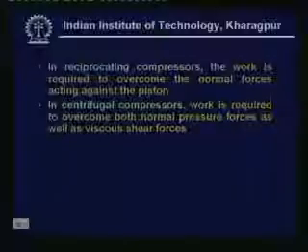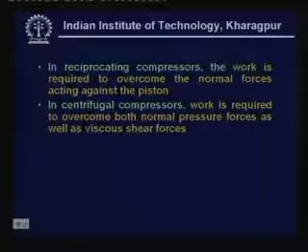Whereas in centrifugal compressors, work is required to overcome both normal pressure forces as well as viscous shear forces. So here the refrigerant has to flow against an increasing pressure. So you have a normal pressure acting on the refrigerant. In addition to that, it also has to overcome viscous shear forces. So the work input is required for these two purposes.